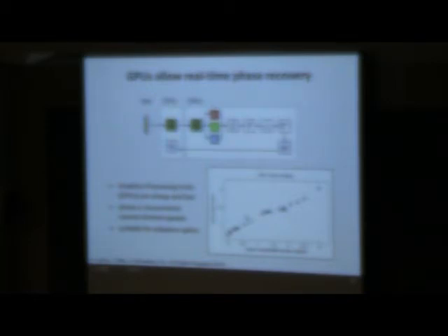The problem is that if you look at the spectrum, I wish I had backup slides, but if you look at the spectrum of a Foveon camera, kind of like red, green, blue, they say that's good because you can really pick up these colors that are in between the 2 channels very nicely. So they say you get better representation of those colors in the middle, but that's really bad because we want our colors to be separated. So I say it doesn't matter, but if there's a lot of crosstalk between the 2, it could matter. But the Bayer filter cameras tend to have filters that are pretty sharp, and then it's not as big of an issue.